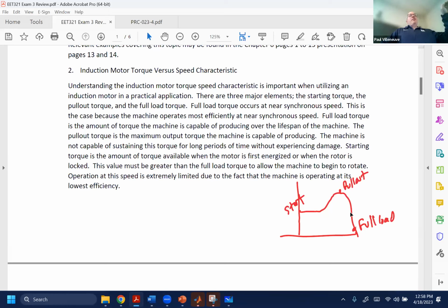And then sometimes what I've seen on the top, I've seen this for electrical, they'll actually buy a piece of angle iron and put that in the top of the concrete. The whole purpose of that angle iron is that it should be perfectly smooth and straight. So when you embed that in the concrete, you have a nice flat plane to work on. Once you bolt things down, you still may need to shim it, depending on if the motor is correct. Because it's very difficult to get concrete to be perfectly smooth, you'll literally just buy shims and put those under the feet and shim it up or down as necessary. Yep. So very, very common.